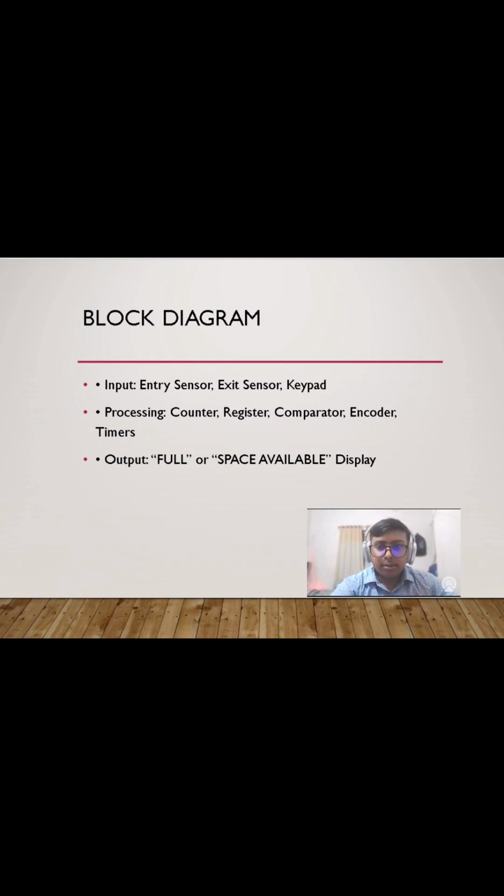Yes, and let's talk about the limitations and theoretical upgrades. So, current limitations and their theoretical solutions. First, the 3-bit counter limit. The problem is it can store a maximum of 7 cars, and the solution is to use an 8-bit counter. It can store 255 cars with carry logic.